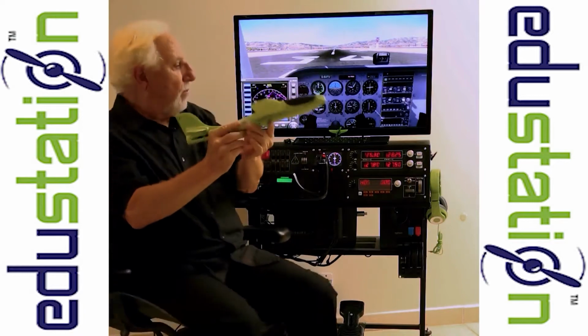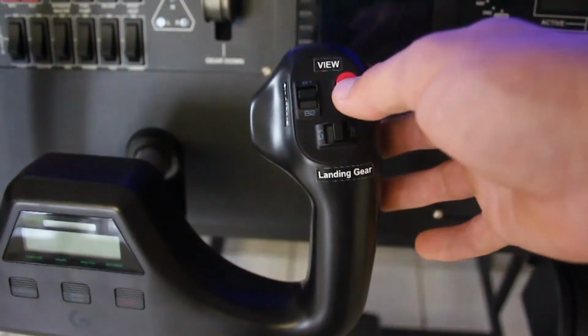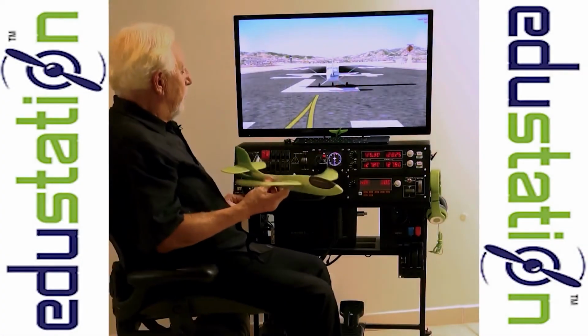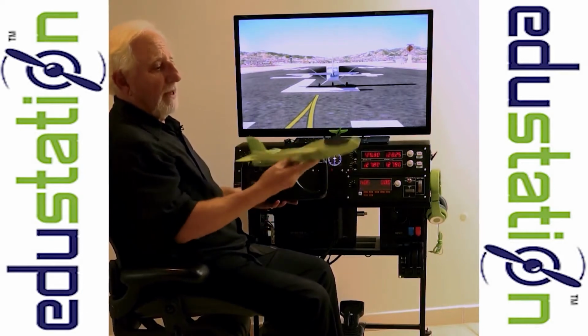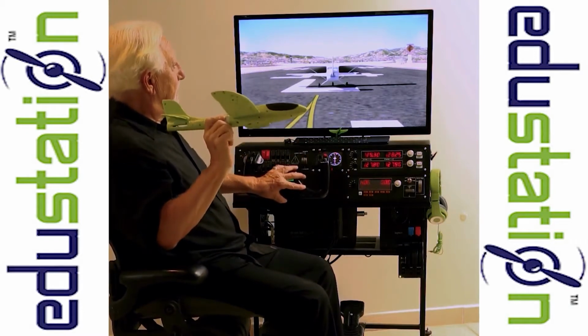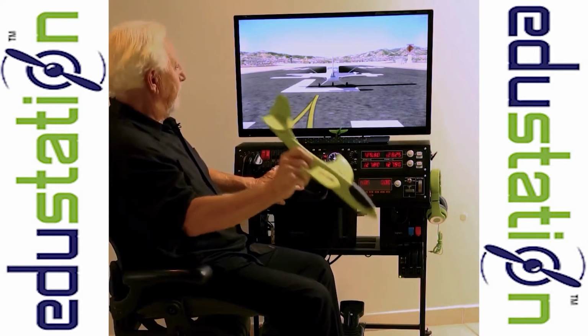The controls that we use, now I'm going to press the red button here to switch the view to the outside of the airplane. When we pull out on the yoke towards us, the elevator goes up and we get pitch up. When you push the yoke down, we'll get pitch down, the elevator goes down.